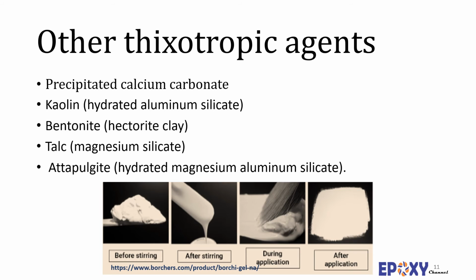Talc is a hydrophobic and organophilic filler, often used as an extender in epoxy adhesives and sealants, but it also has flow control properties. Talc is used in higher solids, high viscosity applications such as caulking compounds, automotive putties, mastics, and sealants. Thin platy particles have aspect ratio varying from 20:1 to 5:1.